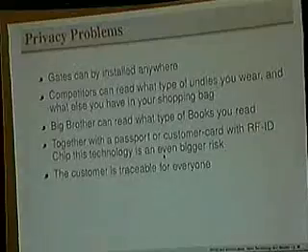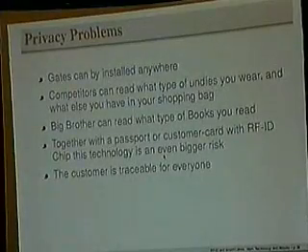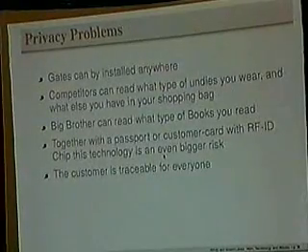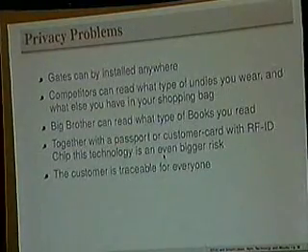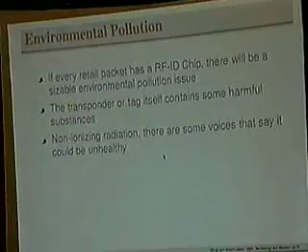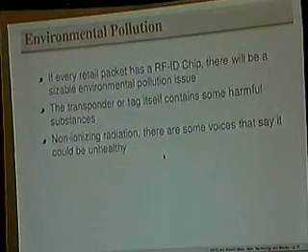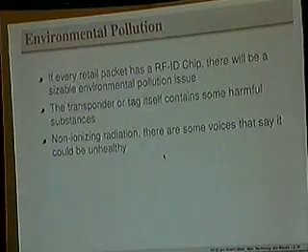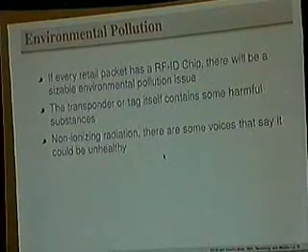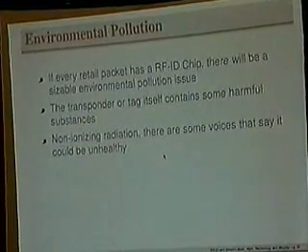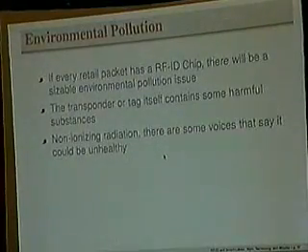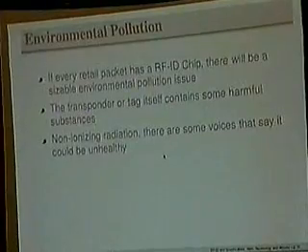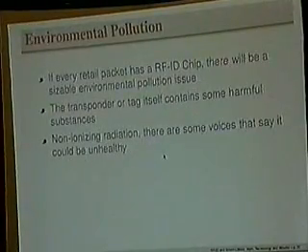The UID, or the administrative block, looks like this. This is a UID block. You have this unique serial number followed by the manufacturer ID and ended with an E0 hex as the end of this serial number. As manufacturer ID in the ISO standard, you have at this moment a few companies, but you see it's a byte, so it's still extensible.